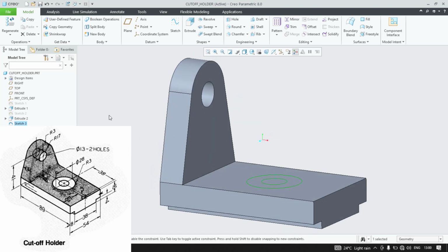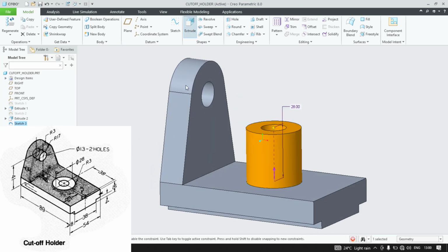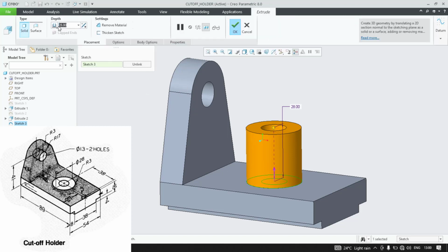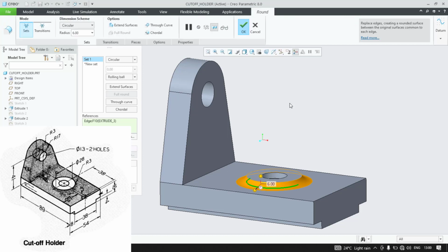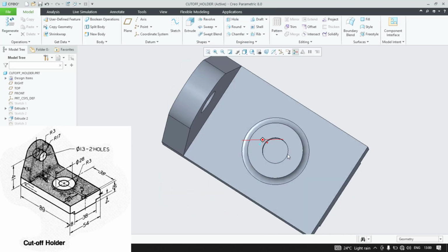Okay. You can simply extrude it up to 3 mm. The distance is already given there. So the fillet is needed here. The fillet radius is 3 as well. You can enter the value. The option is just behind the sketch. You can add the value there.